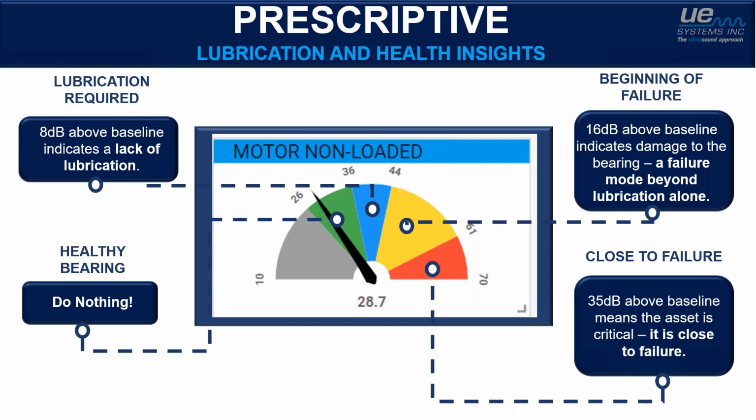So what would happen is if you were to walk out there with a grease gun or use a single point lubricator and put a little bit of grease in, with every pump of the grease gun, as grease enters that bearing, you will see that friction drop and drop and drop. That arrow would slowly move to the left. In fact, it won't move slowly. What we've seen, and I'll show you some case studies, is it actually falls very, very quickly. And by leveraging IoT, you can see this in real time, and people are often surprised: do I stop here? Normally I would have put in 10 more pumps. I'm like, absolutely, you're going to stop there because it's happy. You've restored to that sweet spot.